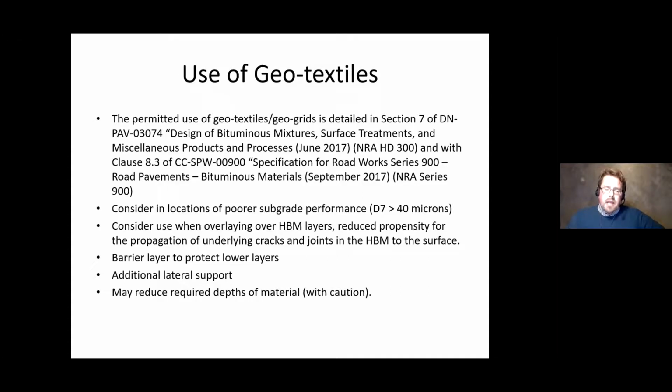And they can reduce the depth of material required. It's not specific how much. Different companies will tell you how much. If you ask your FWD operator, they won't determine how much you can save using your geotextile, because there are too many unknowns. But you can either reduce the depth of material slightly, under caution and under negotiation, or you can get a much longer life out of your pavement, and they are worth considering in the right circumstances. And again, they are expensive and they can be quite costly and wasteful if not used correctly. So I'd caution against them unless you're in a circumstance.